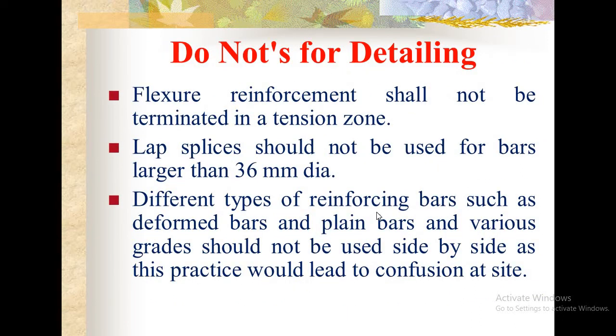Do's for detailing. Flexure reinforcement shall not be terminated in a tension zone. Lap splices should not be used for bars larger than 36 mm. Different type of reinforcing bars such as deformed bars and plain bars and various grades should not be used side by side, as this practice would lead to confusion at site.